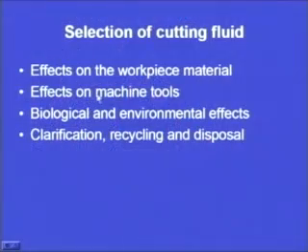Then how it is going to affect the machine tool. As we have seen, water may cause a rusting action on different elements of the machine tool. So, one example can be quoted as water. It should be treated in such a way that it does not cause any rusting action on the machine elements. Similarly, if we choose any particular oil, how is that oil going to behave with the machine elements? If it is going to react, then what is going to be the effect of that reaction? All those aspects have to be seen while we select a particular cutting fluid.